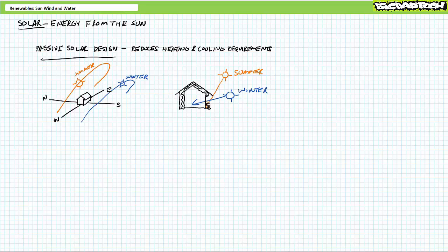In winter, the sun appears at a low angle to the horizon, whereas in the summer, the sun appears at a high angle to the horizon. One way of passively heating and cooling your home is to ensure the southern side, i.e. the sun-facing side, is composed of a high percentage of insulated glass. During winter, the low-angle sun shines into the building, heats the well-insulated interior. During summer, the high-angle sun is blocked by a small overhang or an awning that prevents entry into the structure, keeping it cool.